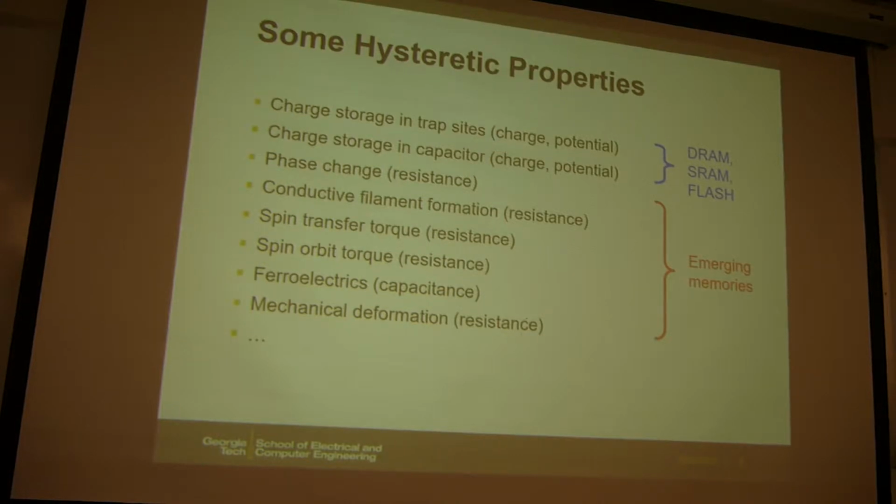And let's look at what really makes a memory. Basically, you are looking for some physical properties of the material to have some hysteresis, because you want to keep a memory state. For, let's say, one single level cell, you just need 0 and 1 state. So you need some state. That means you need some hysteresis in the physical properties.